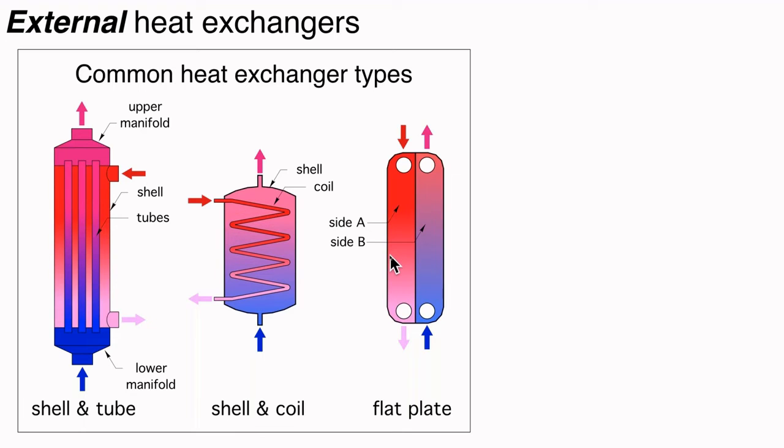And for most hydronic applications today, especially residential and light commercial applications, and I would say, in all fairness, even with larger applications, the flat plate heat exchanger is really starting to dominate the market in space heating and cooling applications. There are other industrial applications where, for example, a shell and tube heat exchanger has higher pressure and temperature ratings that may be necessary in a very high temperature, high pressure environment. But the flat plate heat exchanger has really come to dominate the geometry of heat exchangers in the HVAC market today.